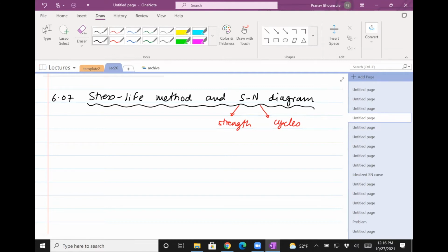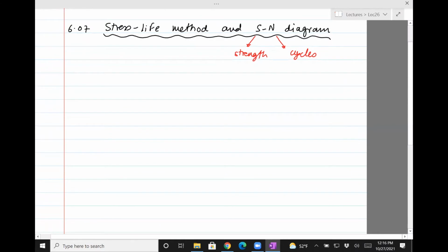So as I said, this method is based on laboratory tests, right? You need to devise an experimental protocol where you'll have a test specimen, like you had in the uniaxial strength test. You'll have a loading condition, and once you have that, you'll observe how things fail and make a plot. In this case, the SN plot. From the SN plot for different materials, you make some hypothesis about how things behave, and then we'll have those points on this curve and sort of model it.